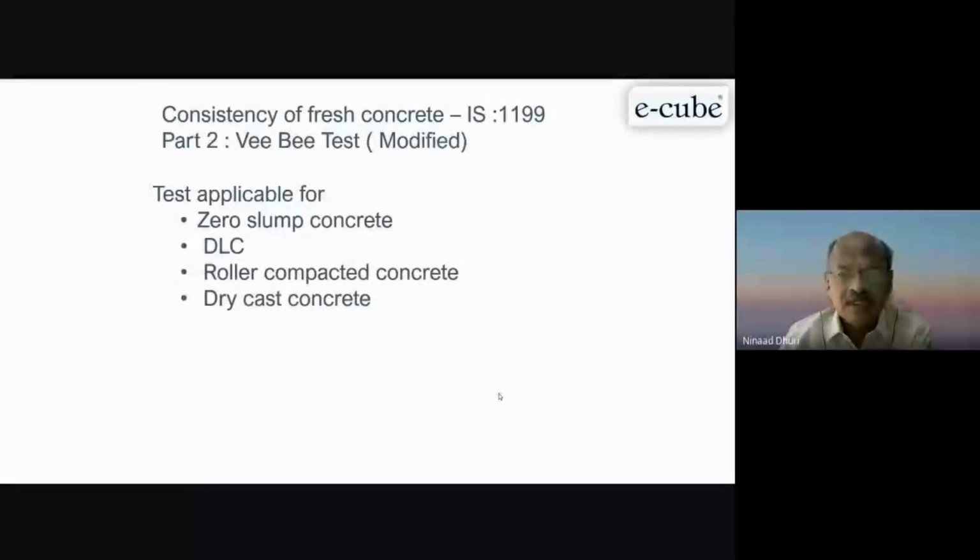As I said, it is generally used for your pre-stressed concrete sleepers. When you prepare, you must have seen it in the literature. It is a very dry concrete, it's very heavy, and high frequency vibrators are used for that. Because it is very high strength also, and requires minimum paste to have minimum shrinkage, because this is a pre-tension sleeper. So there we need a zero slump concrete.